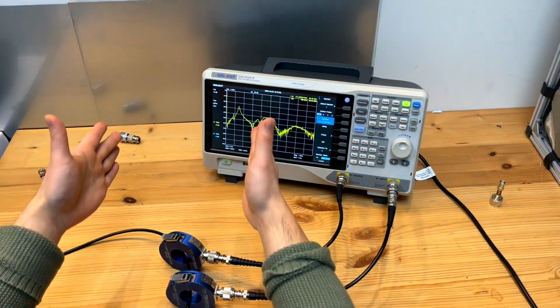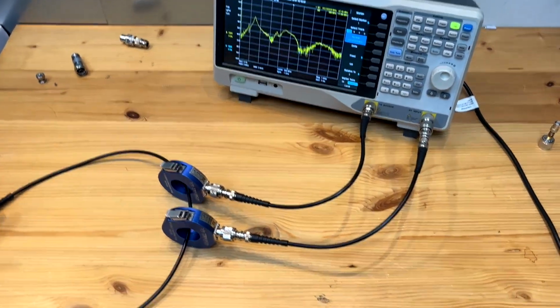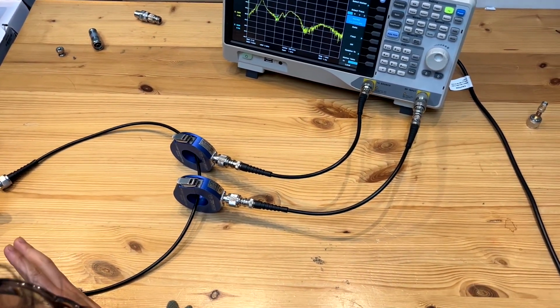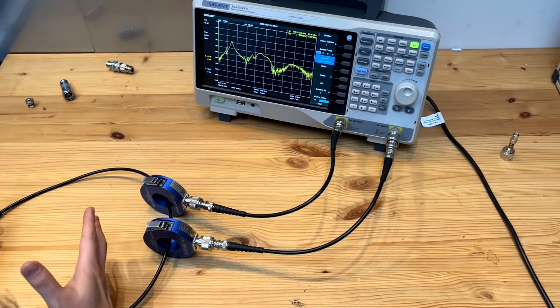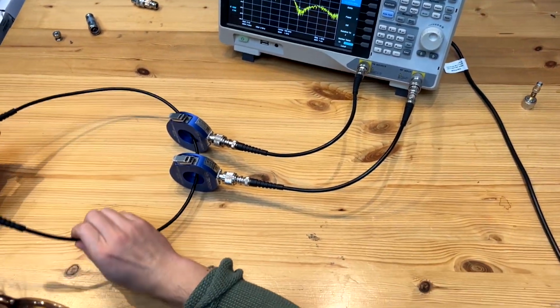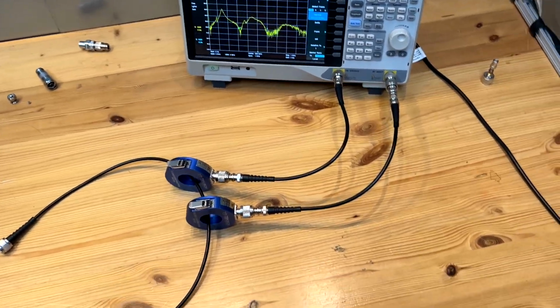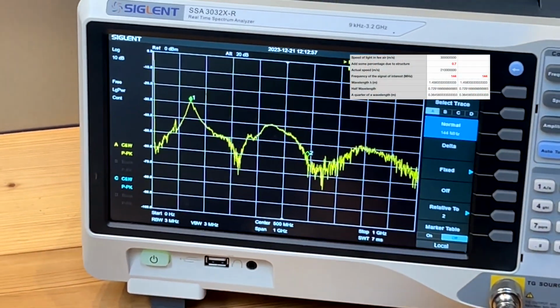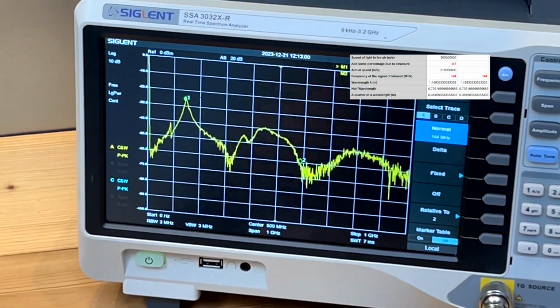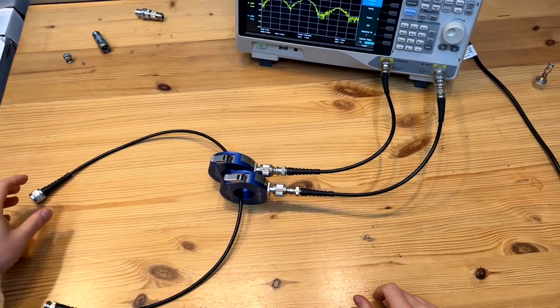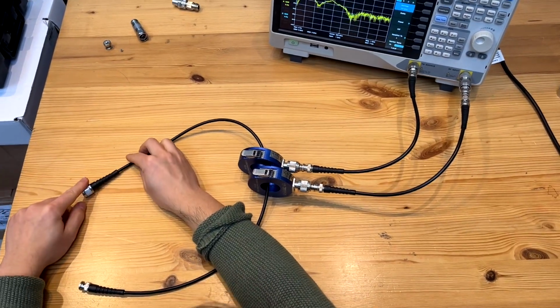And if you measure, because we know that the length of this cable is about 80 centimeters long, you can translate that into a half wavelength antenna, and then you will see the resonant frequency of this half wavelength antenna is 144 megahertz, okay?